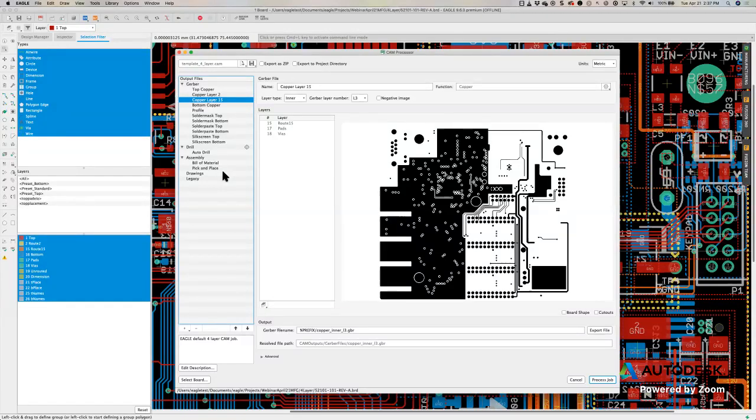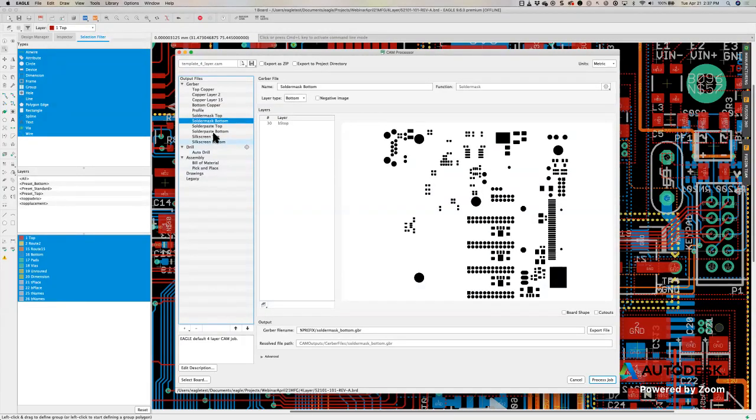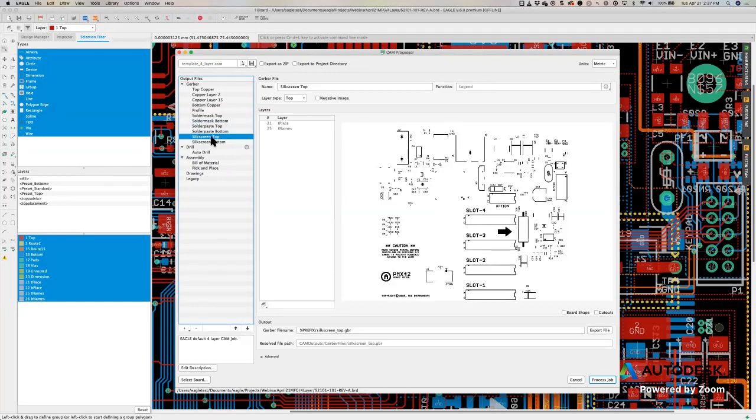Now, let's say, for example, I wanted to import a logo, and I imported that logo. For Eagle to import graphic files, you should be using a monochrome bitmap file. I mean, it does support 16 layers, but every layer is a different color, so it gets really big. So I like to recommend that you only do monochrome bitmap files. Eagle can import those using a tool that we have. And let's say I imported that file and I created a layer 110 called logo.